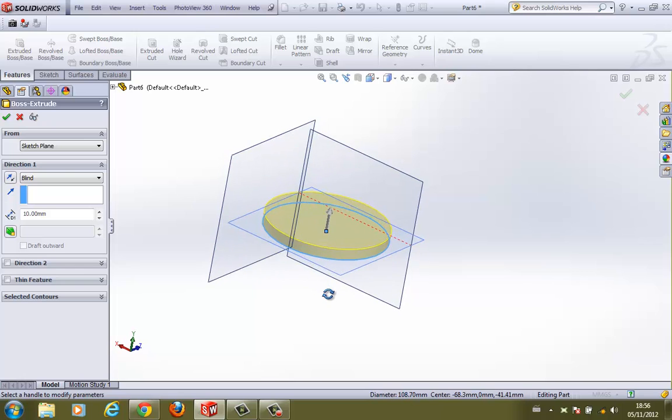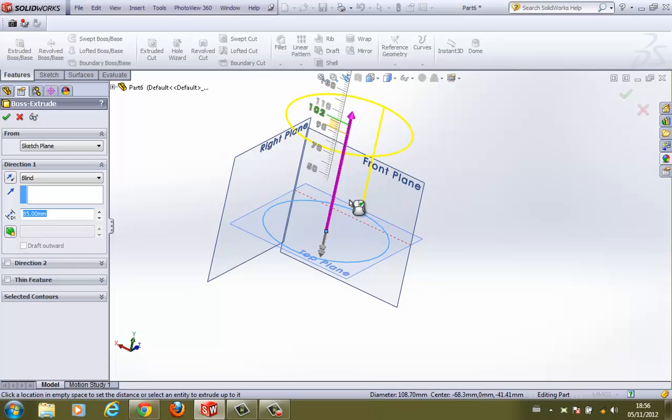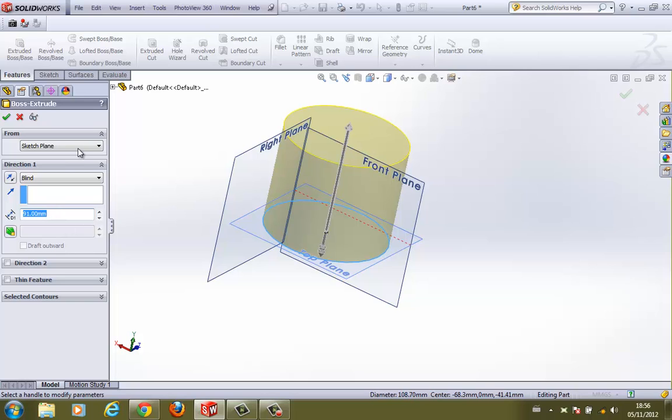Couple of ways we can go for the rest now. We can drag onto this gray arrow, give it some sort of a height, some sort of depth if you want, or from over here in the properties manager we can toggle this extrusion like so. Or if you have a specific number in mind, for instance 120, I'm going to use my keyboard to type in 120, hit enter, and then we can commit to that.